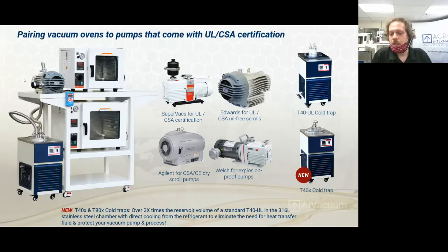And for that reason, we designed our larger capacity T40X and T80X cold traps, which are negative 40 and negative 80 Celsius, 316L stainless steel cold traps, which have 20 filtration plates that offer more surface area for greater residence time and greater recondensation capability in a food and pharma grade 316L chamber that allows you to actually drain mid-process as well. And we have a video on how to do that even out of a vacuum with our peristaltic pumps on our Instagram, Across INTL. So I recommend everyone checking that out.